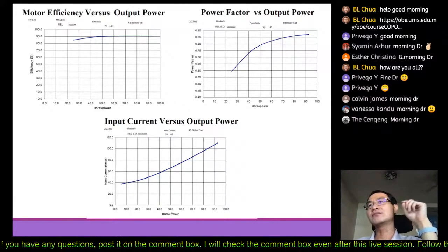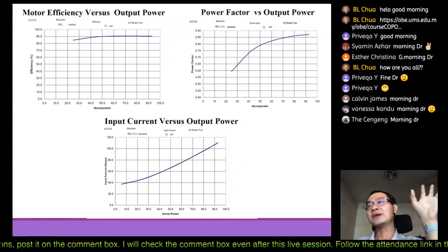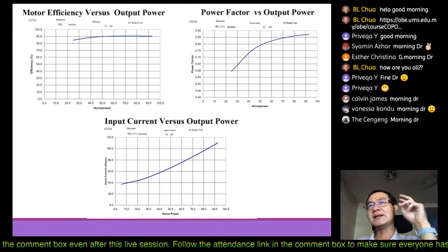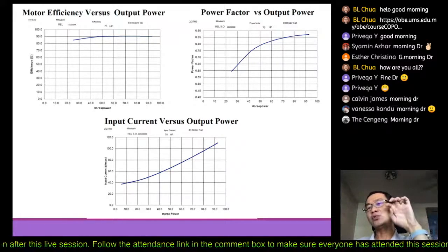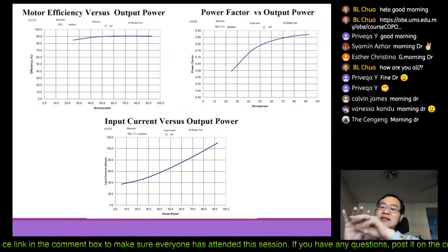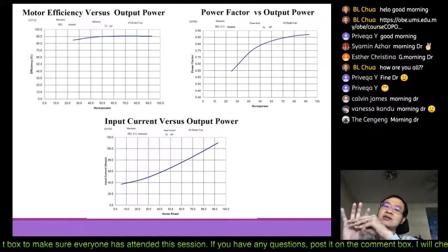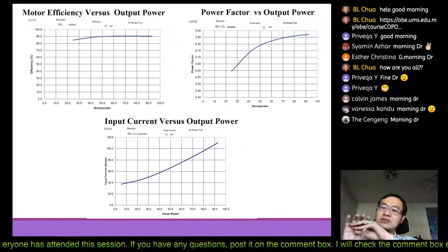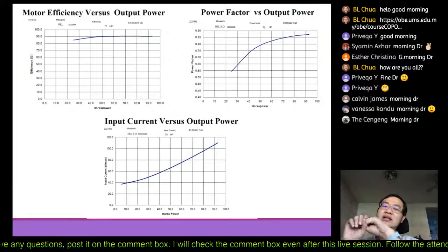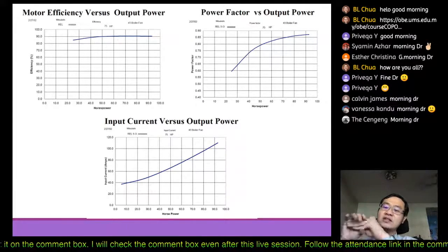Probably, if the fan blade remains the same, there is a slippage between the belt and the pulley. When it slips, whatever you draw can rotate easier, because the system doesn't connect properly. The load is lesser because of the slippage.